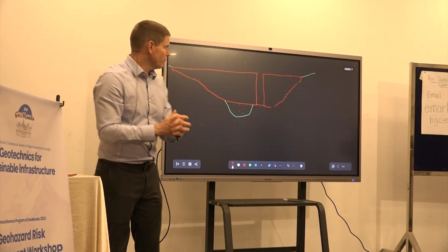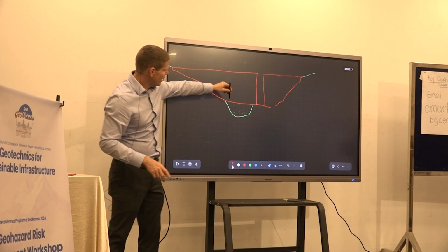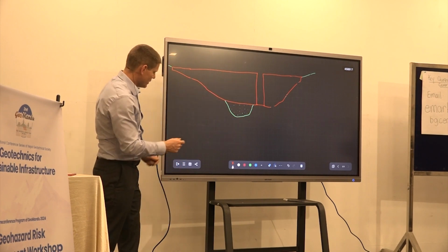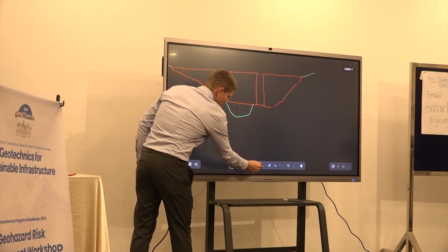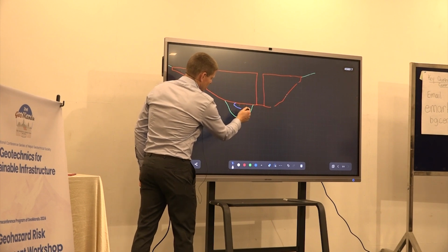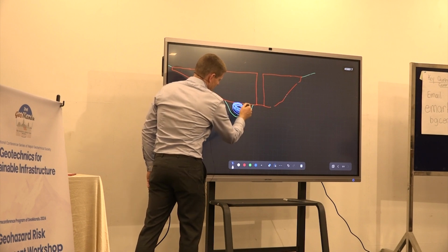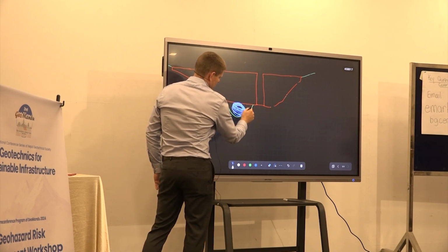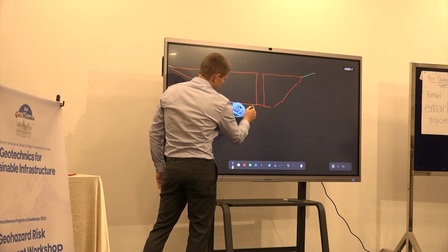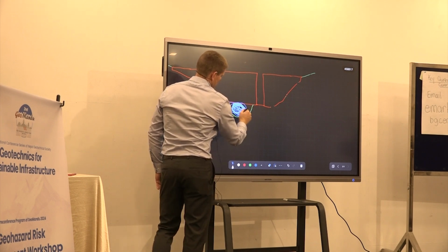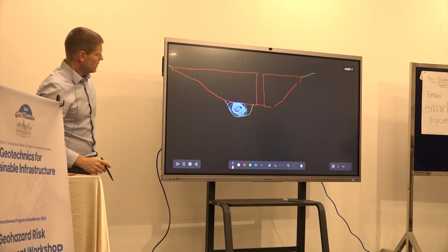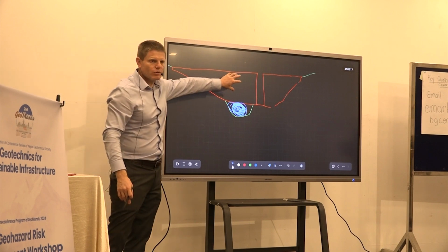So for the specific failure mode of erosion, if we imagine that we have a pipe that forms here underneath our structure, and it erodes away our dam. So let's say we have piping that occurs here. We have a large pipe that erodes all of this away. What would be the consequence on this dam?